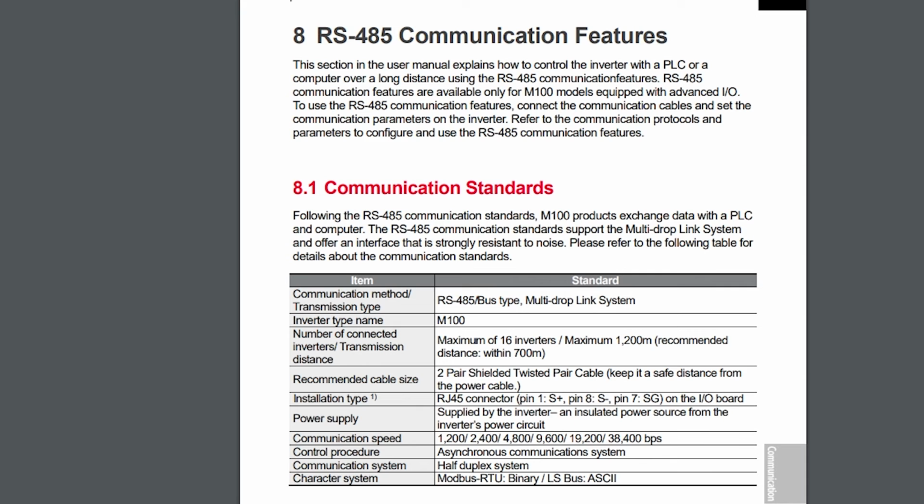So how do we get this old girl wired up? We've come down to the RS485 communication part of the manual, and going through, it all looks very, very normal. There's nothing that jumps out and says anything is weird or different, apart from this installation type bar. We're on an RJ45 connector. So your VFD might just be a couple of terminals that you put the data wires in. Here, it has to go through an RJ45.